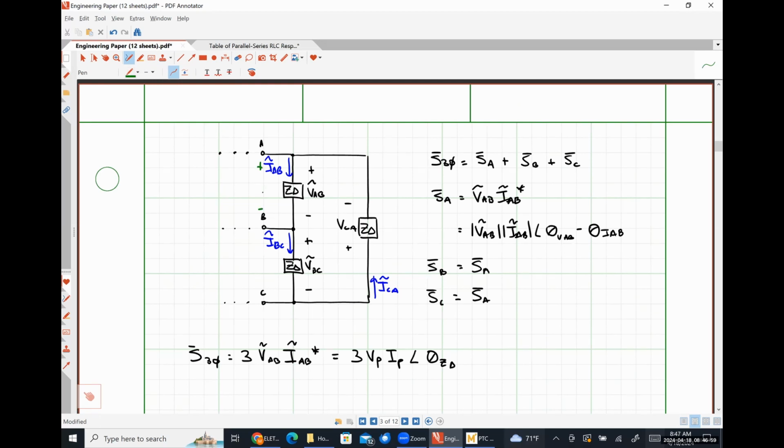So here's our line voltage, VAB, our line voltage, VBC, and so forth, right? So what's the relationship between our line voltages and our phase voltages for this delta connected load? They're the same thing. They're literally the same thing.